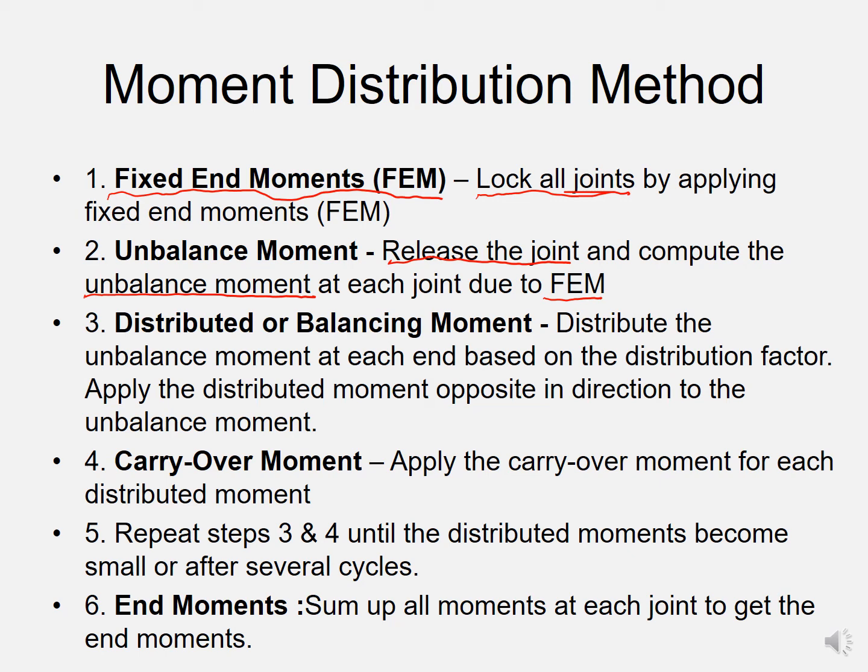Third step, we apply the distributed or balancing moment, and this moment is applied opposite in direction to the unbalanced moment in step number 2. The balancing moment is distributed to each member depending on the distribution factor of that member.